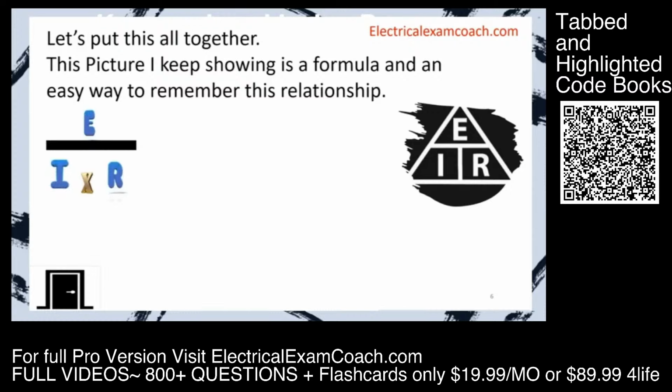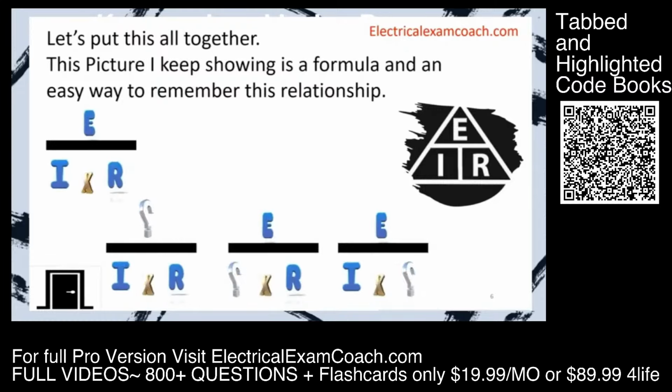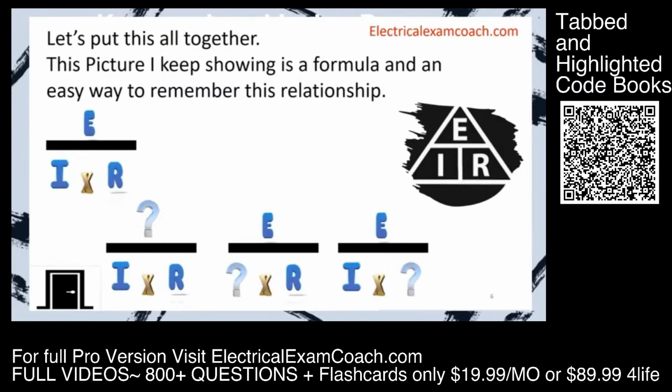And what this relationship is saying is that as long as we know any two, we can always find the unknown. Now, if you're like me, I don't like a ton of math, but thankfully all the math in this program is 6th grade math. If I can do it, you can do it. Trust me. What this relationship states is that if I know any two, I can always solve for the unknown. If I know I and R, I can just multiply. If I know E and R, I can just divide and it'll let me know what I is. If I know I and E, I can just divide and it'll let me know what R is. And we're going to break this down piece by piece and show you that you can do it.